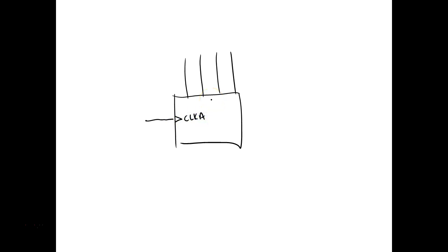So y'all hear what Brian said. So what we're doing is this is QA, this is QB, this is QC, this is QD. And then we have to take this guy right here and feed it back into clock B. So for clock B to change, QA feeds QB.